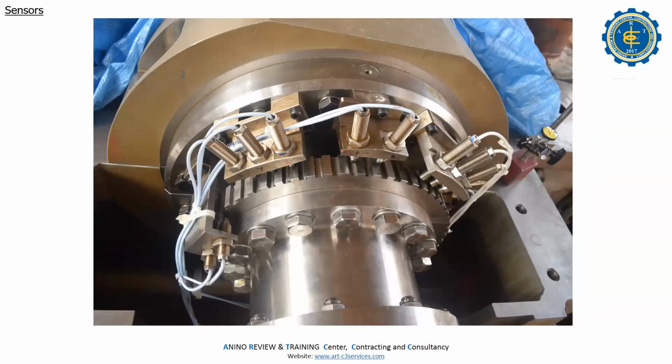So this one. Here, you have the proximity probe. We have also the speed sensor. So this is the radial, this is the axial. How many proximity probes do you have? 2, 3, 4, 5. We have two axial, horizontal, and two radial, X and Y.